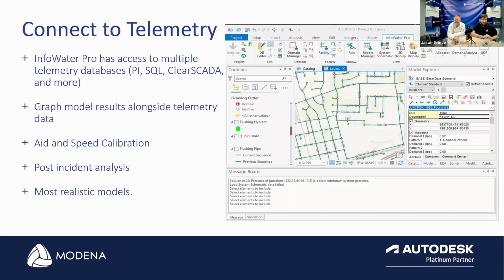Now, with this, we can graph the live data to our actual model in real time. Using ClearSCADA data or even accessing the data through the Oracle servers, we can see what our model is predicting to happen and what is actually happening on site. And if we have any deviation between those 2 variables, this allows us as the users to create a lot more accurate model to get as close as possible to that live data that we are seeing.